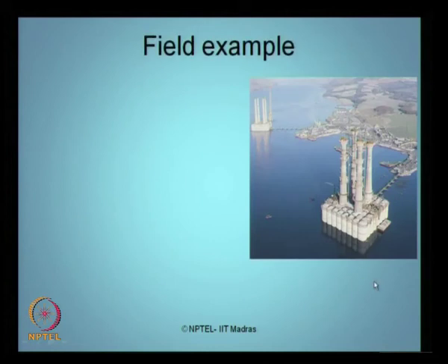From this photograph, you can very well see there are many interesting towers constructed, which are supported at the bottom by a large number of caissons, which are essentially void spaces when they are floated. Then they can either be ballasted to achieve a specific draft, or the void spaces of these caissons can also be used to store crude oil which is explored from this platform. You can see one over here which is being floated from the offshore, and one very close to the shore which is getting floated now.